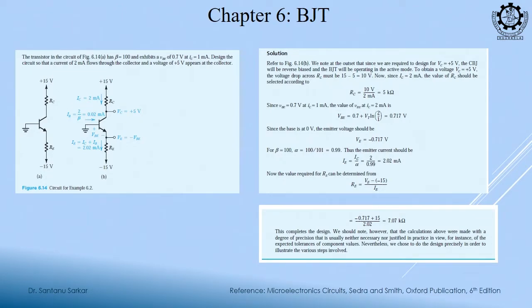Yes, because emitter voltage is minus 15, base voltage is 0, the difference is 0 minus of minus 15, which is equal to 15. So, effectively the base emitter potential is positive, but if this potential were at ground, then this circuit may not work. Because this is minus volt, this potential is positive, the base is higher than the emitter voltage, so the base emitter junction is forward biased. Because this is a very high voltage, you are sure that the base emitter junction is forward biased, right.